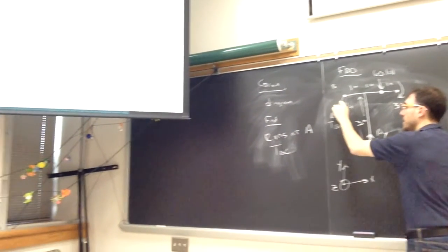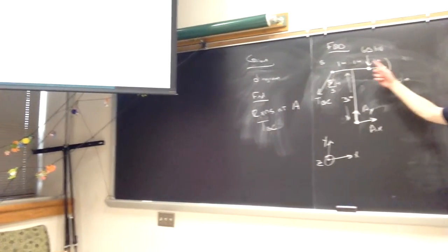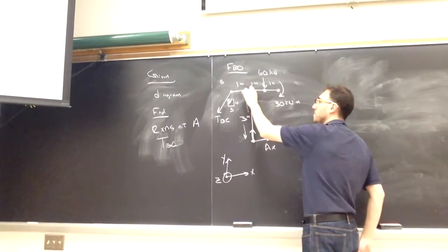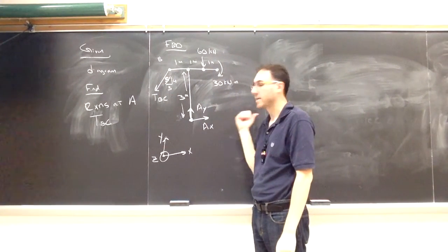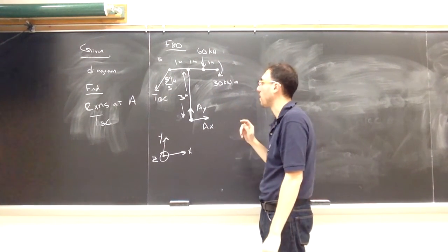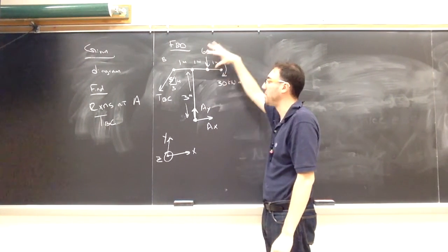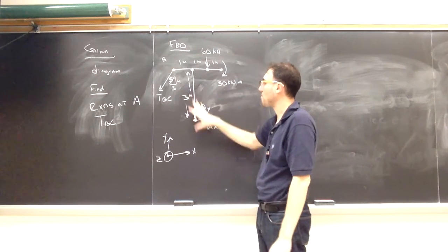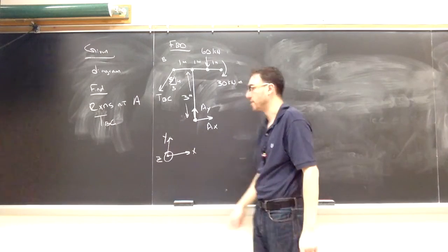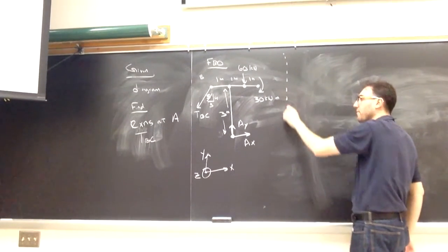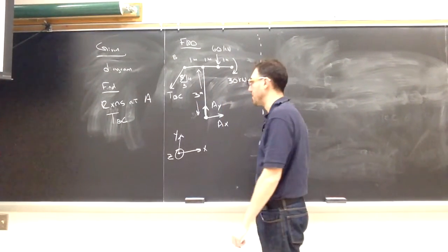So I can represent its dimensions with the ratio triangle. I've included the lengths of these different segments. I have the angle of this force. AX is to the right, AY is up, so that's taken care of. So all of my dimensions are here. All of my forces, both external and from my reactions, are represented. I have my object, I have my right-handed coordinate system. So this would be my complete free body diagram for when my steel frame is my object of interest.